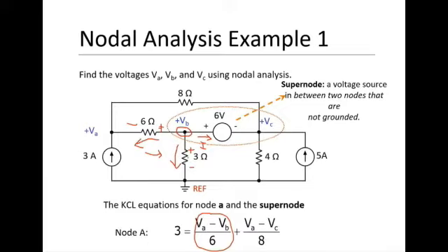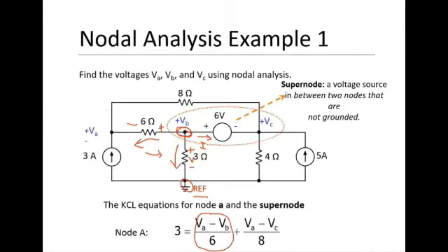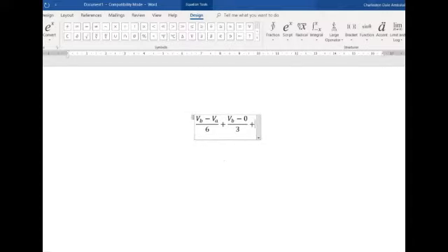Again, this is the voltage difference on the resistor, which is defined by the potential here minus the potential here, which we set at reference. So it would be 0. So that's VB minus 0 divided by 3. And finally, there's some current that is going through this voltage source. Let's call it I. Then that's just plus I equals 0.